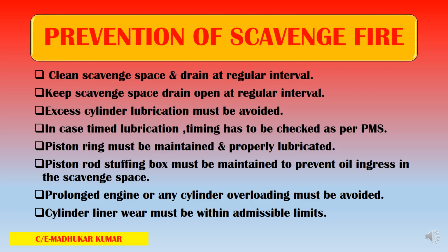How much scavenge drain is coming every day when the engine is running is to be monitored. If everything is normal, there is a certain amount, which varies from engine to engine. So if that flow is okay and the drain is not choked, then whenever possible, on a voyage to voyage basis, the cleaning is to be done. Keep the scavenge space drain open at regular intervals. Yes, when the engine is running, you can keep it.